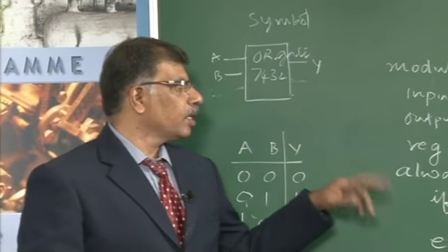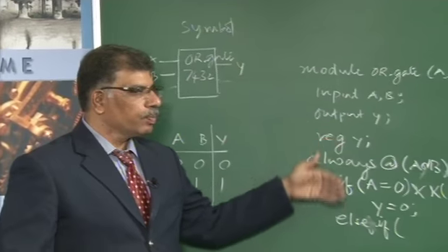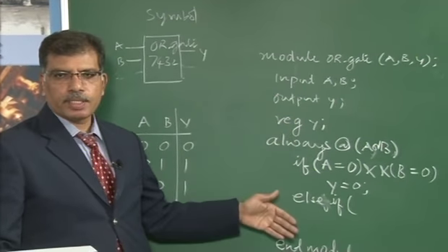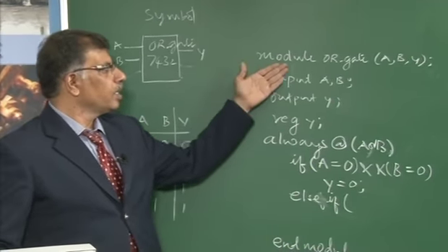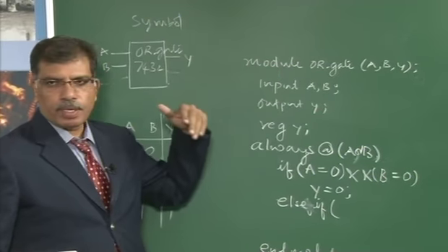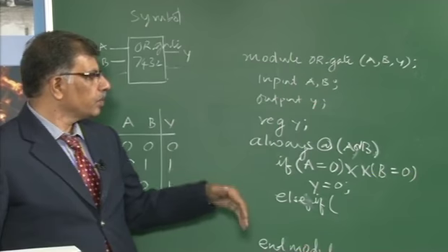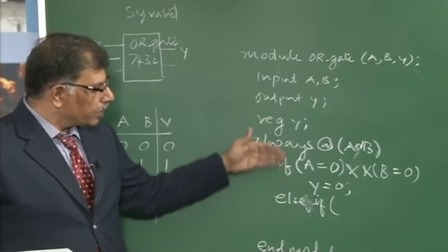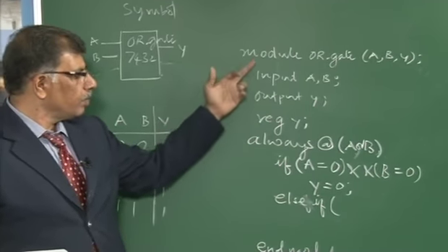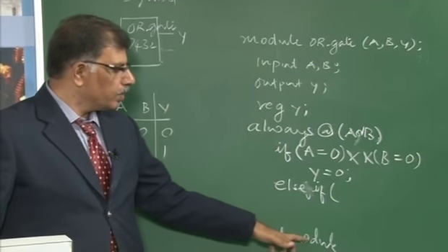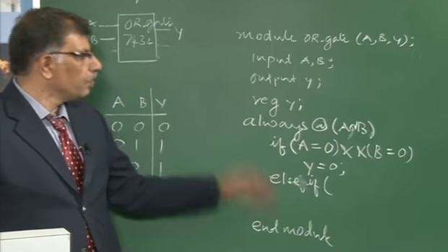But in case of a Verilog model, you will not have two explicit parts to describe an input port as well as functionality. You will have a single definition or syntax called a module. In that, we declare the inputs and outputs as well as the functionality within the same module, and it has an end module which specifies that the description is over.